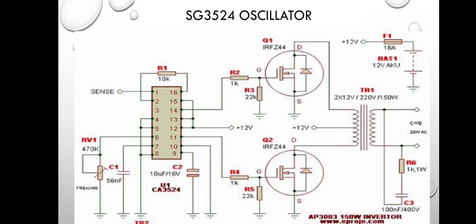So we'll be using it for our battery low circuit, so that when your battery is low, we use an operational amplifier to signal this pin 10 for a battery low shutdown.